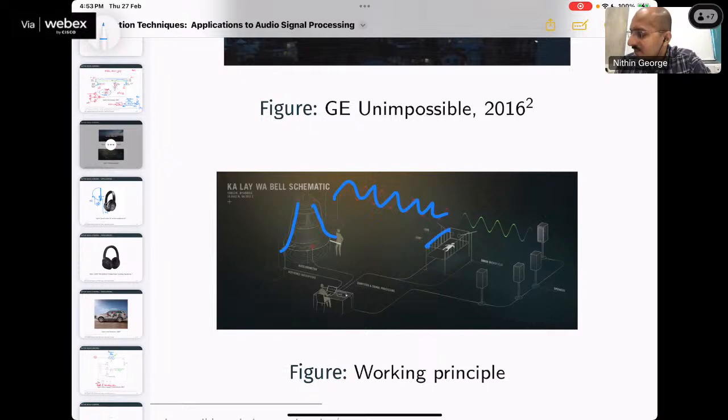So they keep a baby here. Baby is here. And they want to cancel the sound near the baby and not cancel the sound for everybody else who is around the baby. Understood? Because ANC is a local cancellation. In the sense, wherever you keep the error microphone, only around that region you will get cancellation. Other regions you don't get cancellation.